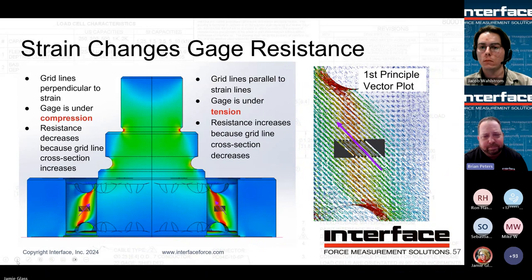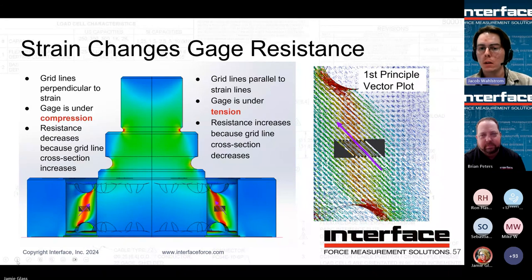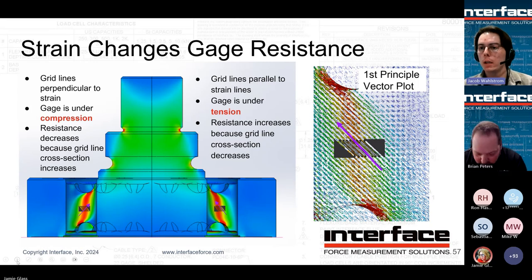That's a good point to bring up about the 1800 series, because not only do they get the integral stud, they also get double gauges, and you can see that the nonlinearity of one gauge being misaligned one way or the other is somewhat random, right? So by doubling the amount of gauges, it can help cancel out any nonlinearity issues.